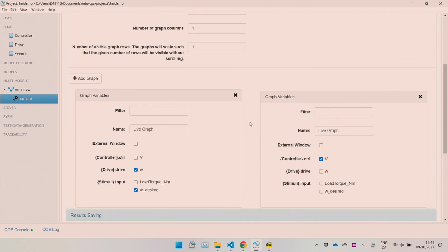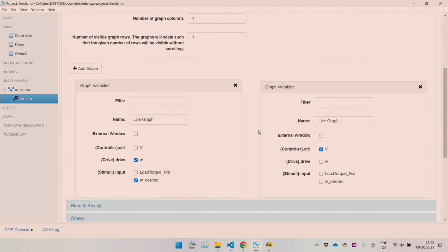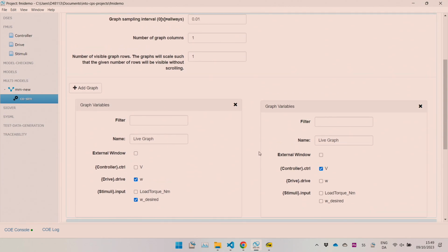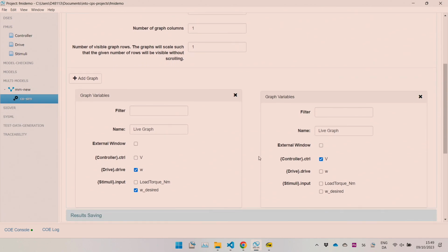Just a question, please. You are performing co-simulation, so my understanding is that each FMU is solving its own equations, and then when the convergence is attempted, you share your data according to the time step. We're not really doing convergence. We're just assuming it converges after one step. Ah, okay. So we're doing a weak coupling co-simulation.